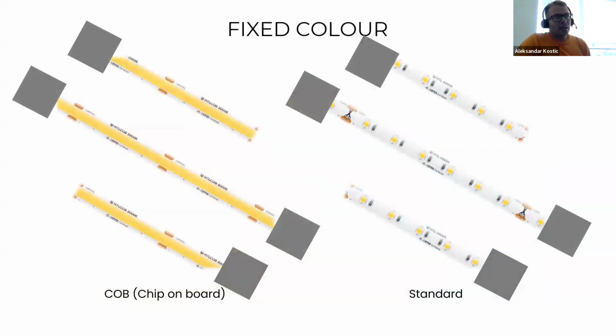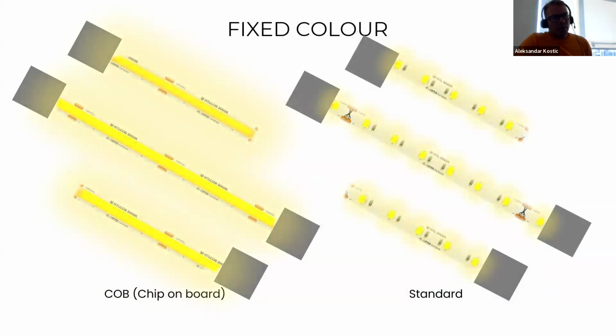On the other hand, we also differentiate between different types of LED tapes. Regular LED tapes will have discrete lights on the tape itself, which can potentially mean you don't have continuity of the light. But generally, using extrusions and lenses will diffuse the light so you have continuous light without noticeable discrete LEDs on the tape itself.